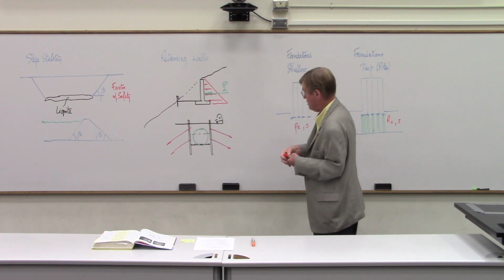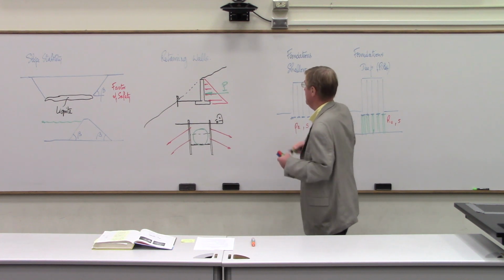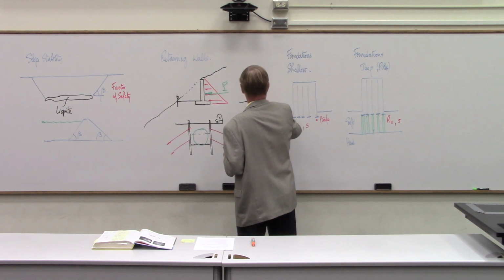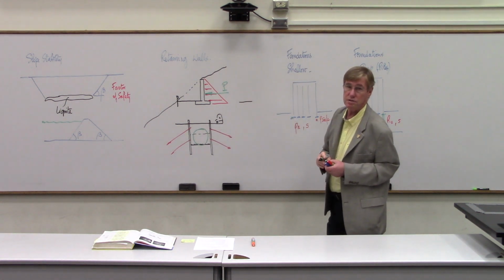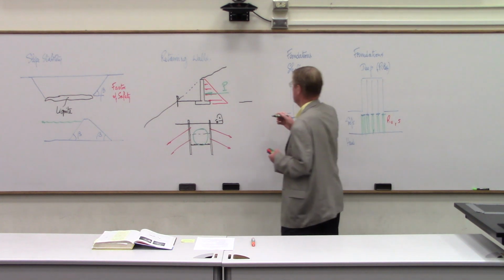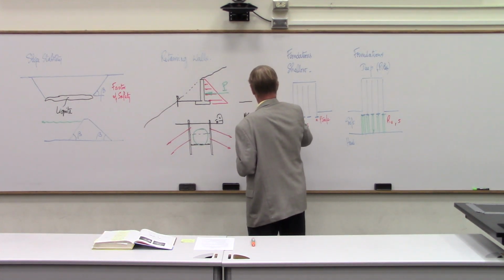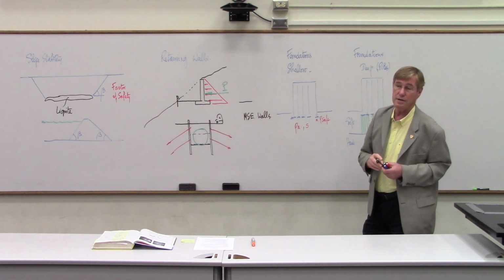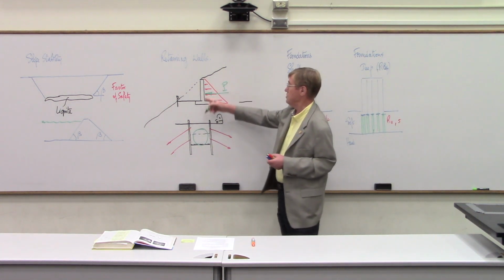There's a new type of structure that's becoming very popular, and it was called reinforced earth, but now it's called mechanically stabilized earth walls, MSE walls. And you see them everywhere along the highway because they work very well, and they're less expensive than these types of walls.